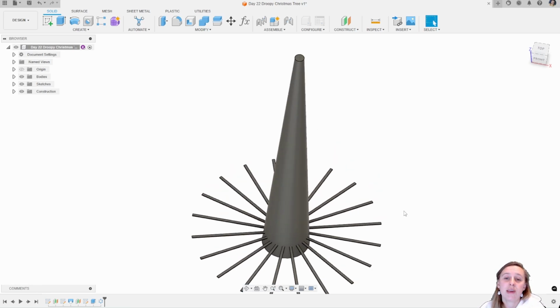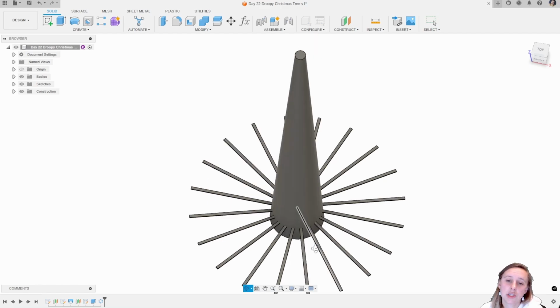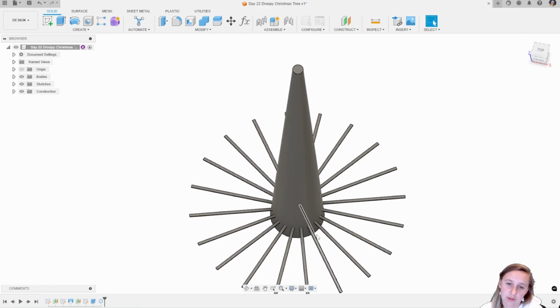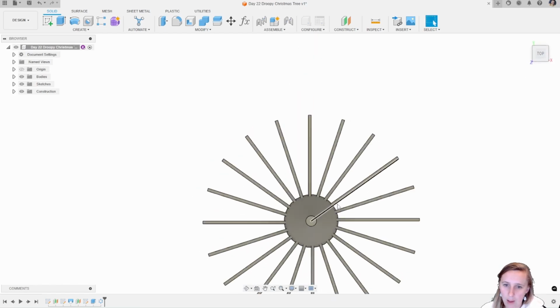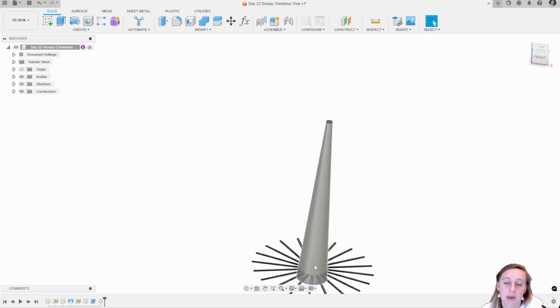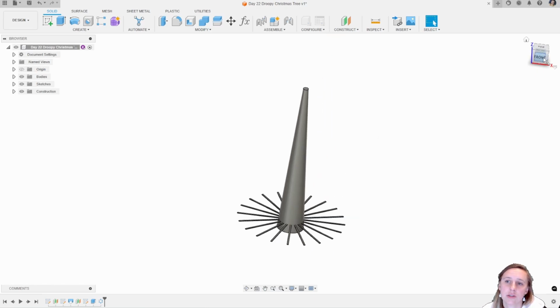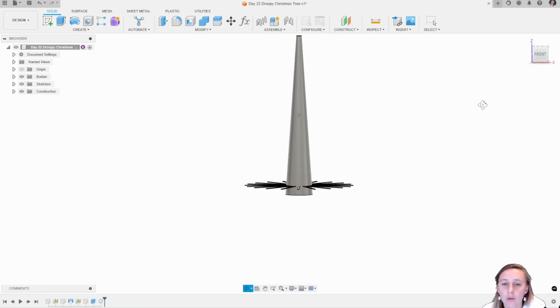Now, if you wanted to be very fancy with your design, you could create another offset plane and do another extrusion offset from this to create a sort of midway design between the two, like here. So you could do another offset design. I'd offset that maybe 1 millimeter up, do another extrusion, and then extrude that up. I'm just going to show you the simple design, and you can adapt this to what you would like it to be. So I've got that design there.